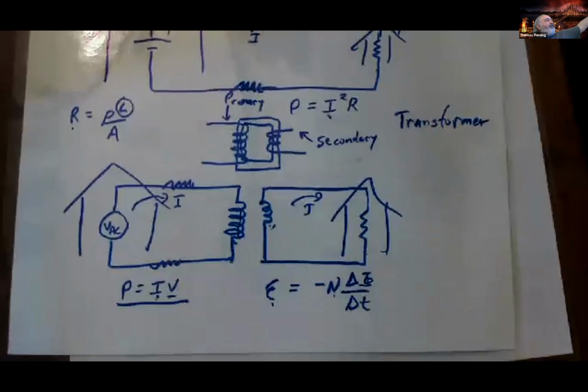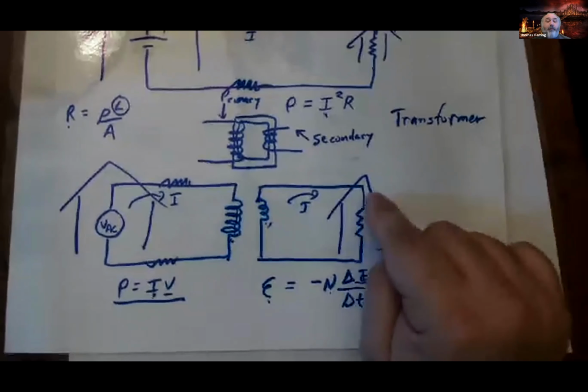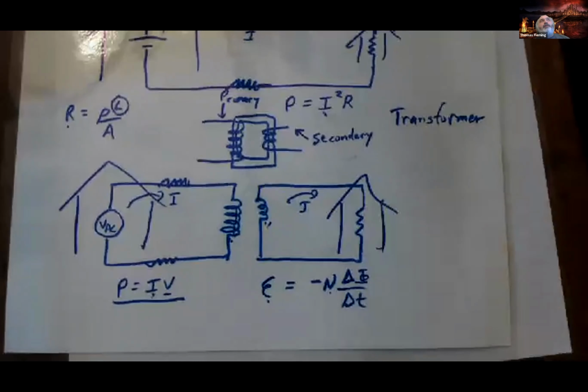Those hundreds of thousands of volts will then travel cross country in the very, very tall, high energy power lines that you might see out in the middle of a field somewhere far from cities. Then they'll arrive at a substation. And so this might not be your house, it might be a substation. And that substation will use a step-down transformer to step 100,000 volts down to something more manageable, like 10,000 volts, or even 1,000 volts.